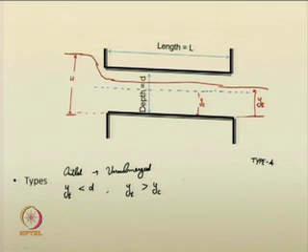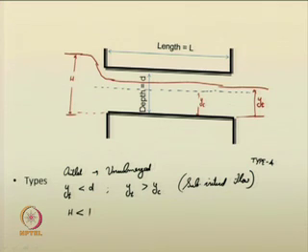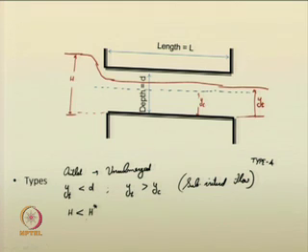So, that means that inside the culvert you have subcritical flow throughout. That is the peculiarity here, and you have H less than H star here. So, here H definitely has to be less than H star, otherwise it would have touched the boundary and all. So, that way we can classify type 4.